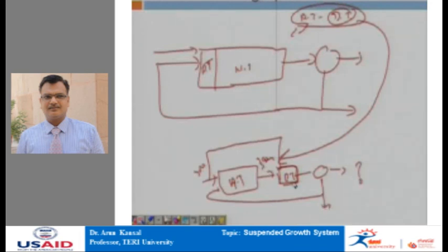The second problem with this system is that in denitrification we always get 2.5 moles of oxygen, and this release of oxygen by denitrification can offset the moles of oxygen required for the nitrification step. So, the net amount of oxygen required in the coupling of nitrification and denitrification is only 2.1, but in this case we have to already supply an excess of 4.6 moles of oxygen, and whatever oxygen is released in this process is not utilized.